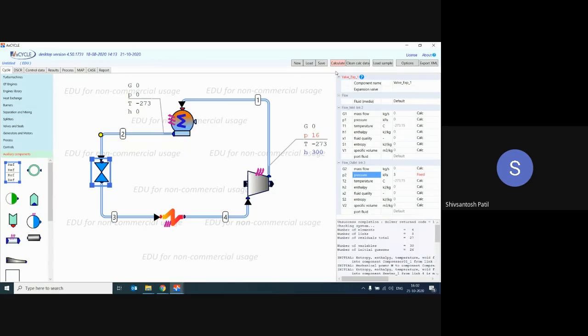And if I calculate this, the error I will get here at the bottom is: four fixed conditions should be defined, two have actually been defined. It is like a problem statement that you give in the classroom. Some of the main given conditions have to be there. So four fixed conditions should be defined for this problem statement, but right now we are only able to get two.